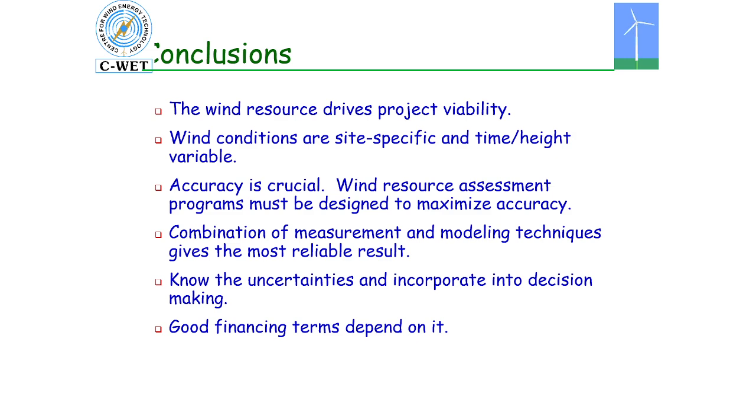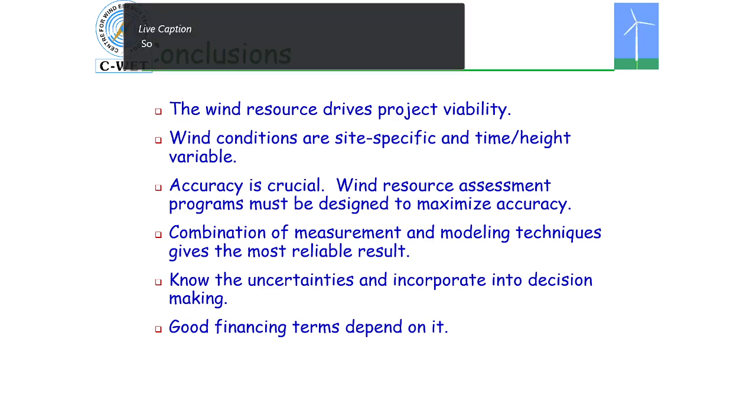So for the project we want to install, the wind mast must be installed a year back to ascertain the data for that particular area. After that, we can proceed with the project. Yes, in a greenfield project, that is the best way to go about it.